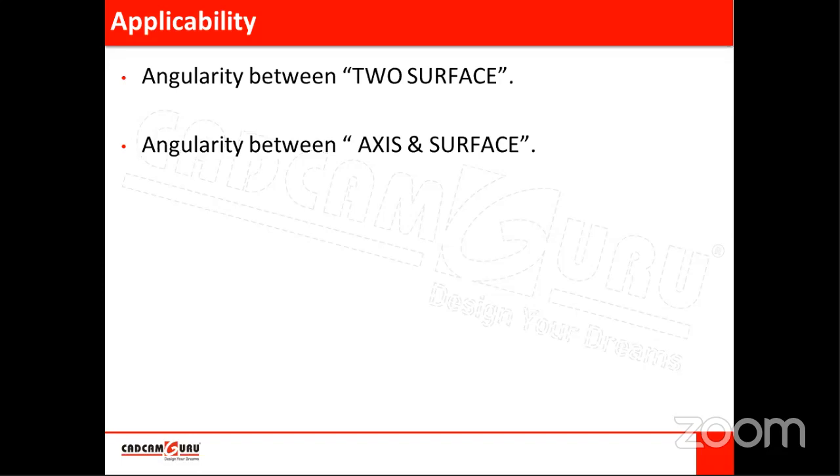Okay, so perpendicularity is a separate characteristic, and angularity is applicable for some angle which is less than 90 degrees. So angles between 0 to 89, okay, or within 0 to 90. Okay, so for such angles we can apply angularity. Perpendicularity is a special case, means a specific case of angularity.